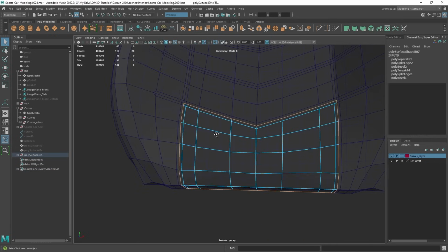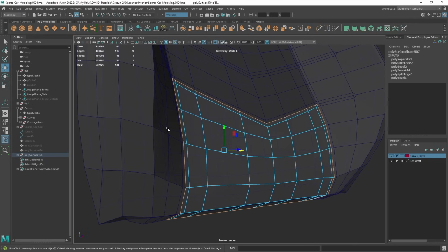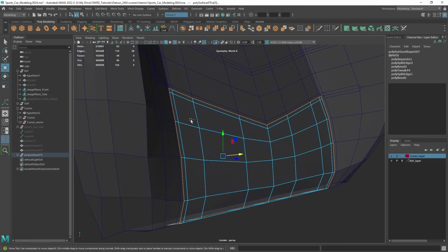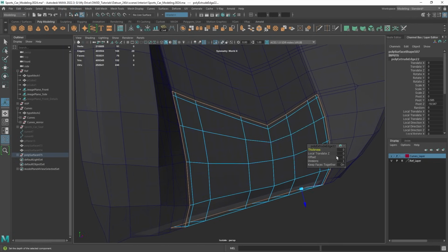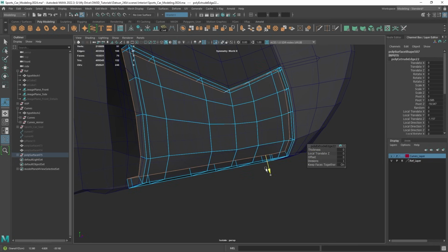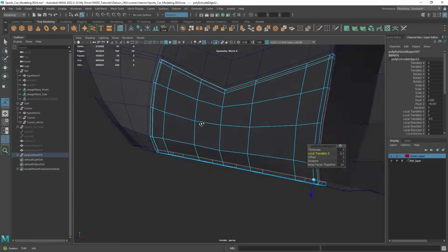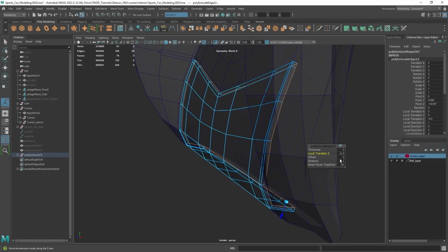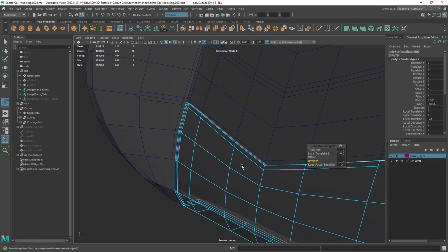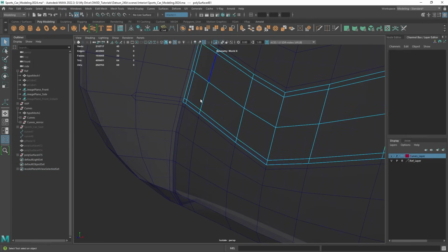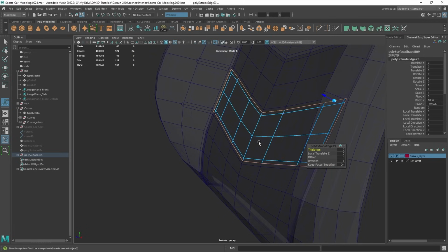So I now want to add in the extrusion. So I hold now Control E or just Shift right click Extrude, and I can move these in. And I typically keep it consistent, so I'll always use the same local translate, which is 0.5 with 1 division, or excuse me, 2 divisions. And then now what I can do is the same thing here. And I will hit G to repeat last, and I'll move it again.